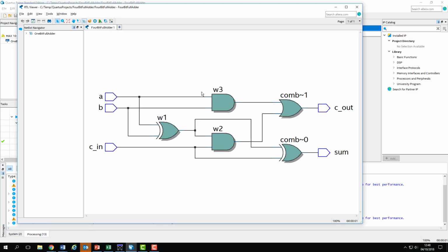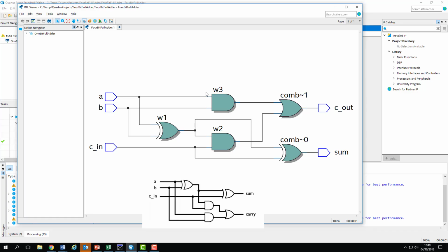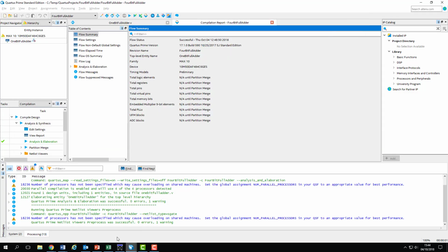Looking in the RTL viewer, we can see that we've got the circuit that we wanted. For this session, we'll just do a visual check compared to the RTL diagram to verify it. We'll be simulating it properly in the next lab session. The RTL presented in the viewer is rearranged, but all connections are correct and we can assume that the module will work as expected. Now we need to push on and create our 4-bit adder module.